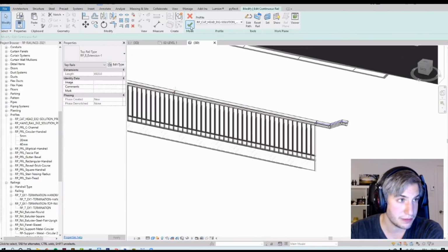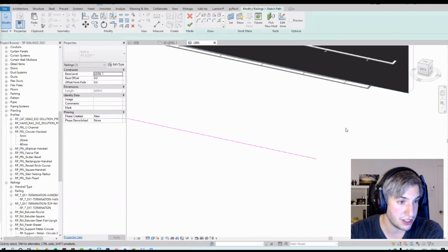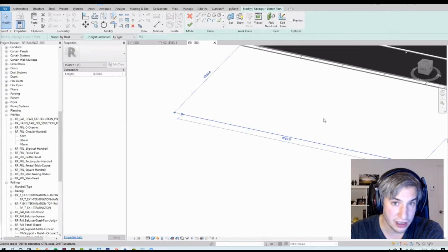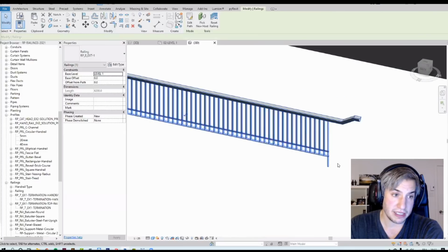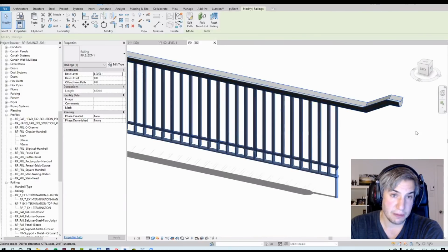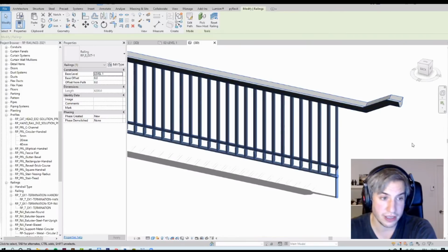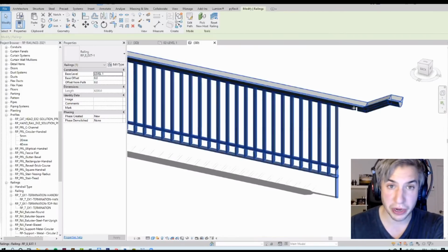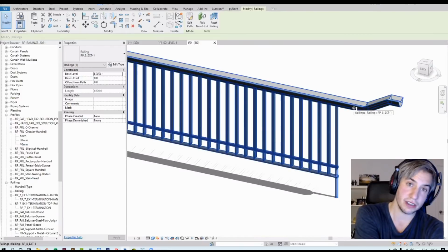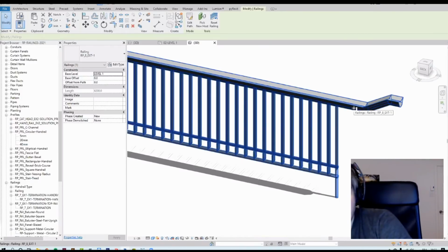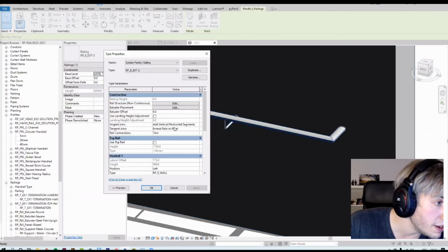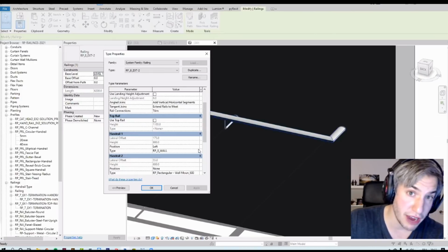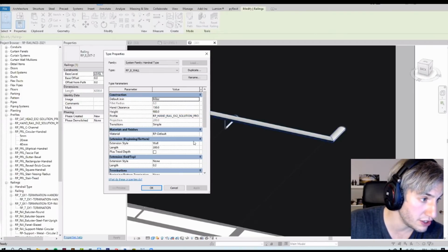Neat. So just to explain to people the magenta sketch line: this is the main part of the railing, and the extension is the part that goes beyond this. It's a place where there are no balusters or intermediate rails. They all stop, but the top rail or the handrail, which can also be used with this extension, can be modified. And there are other styles. There's an extension style that is specific to handrails. It doesn't work with others.